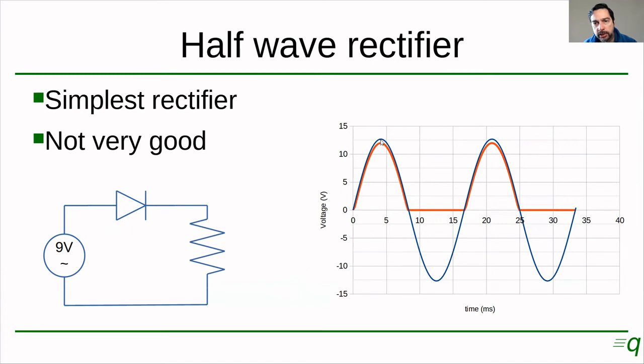There's a difference between this maximum value here and the maximum value here, and this would be your 0.7 volts that you're losing on the diode. So if you have here, say, well, if this is 10 and this is 15, this would be 12.5, and this one here would be a bit below 12, like 11.8. So that's the 0.7 volts that you lose on the diode.